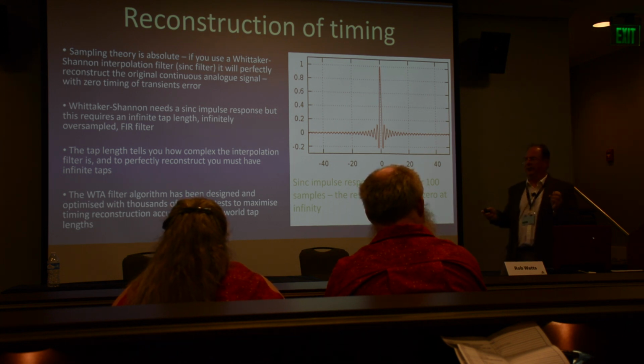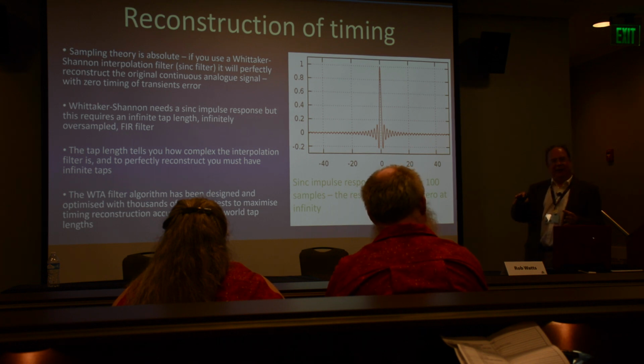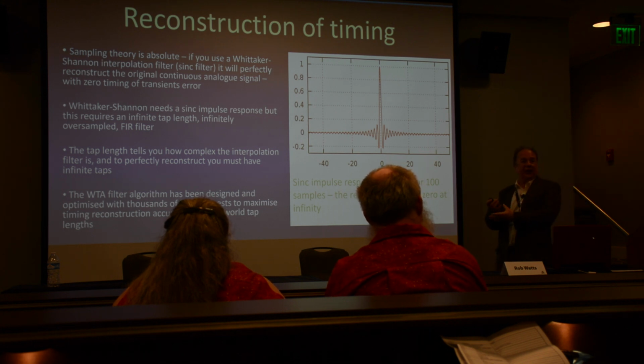So you use something called a windowing function. The windowing function will taper this out so that it makes it a little bit smoother, and then you get much better performance in the frequency domain. The windowing function that I've used has been optimized in a way so that we can reconstruct the timing information to a much better accuracy.